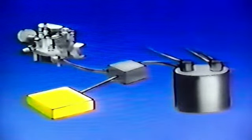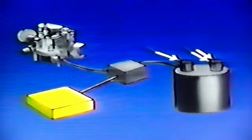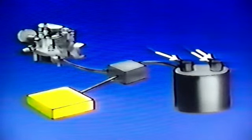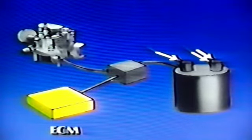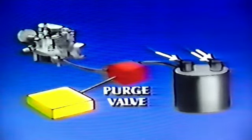When the engine is shut down, the canister collects fuel vapor from the engine and fuel lines. We don't purge these vapors into a cold engine because this could create drivability problems and defeat the emission control functions. Because of these potential problems, the computer looks at coolant temperature and controls a valve that allows the canister to purge properly only after the engine has warmed up.